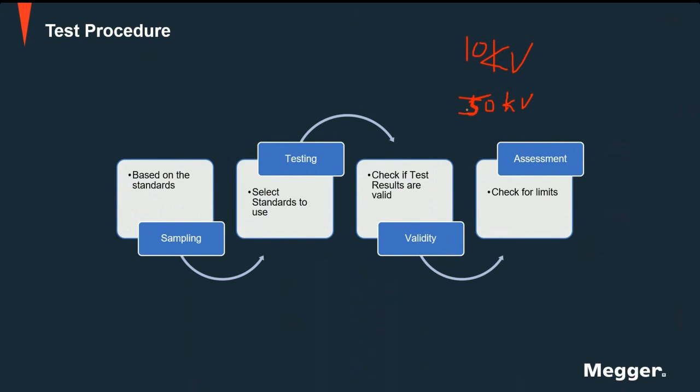Most probably, when you do the test, for example using the VDE electrode, during your first test there are some particles floating inside that cause the breakdown at this low voltage. Then suddenly the particles drop down, so you can have the 50 kV. So your test is not valid because you don't have a homogeneous situation. The oil is not really clear to test.